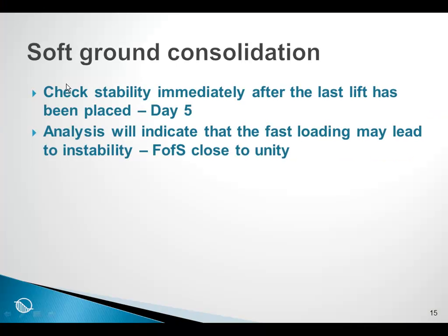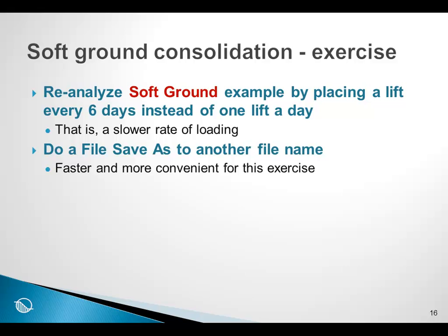Going back to our PowerPoint presentation, we have now checked the stability by placing the fill very rapidly, 1 meter a day, and this analysis indicates that the fast loading would likely result in instability because the factor of safety is too close to unity.